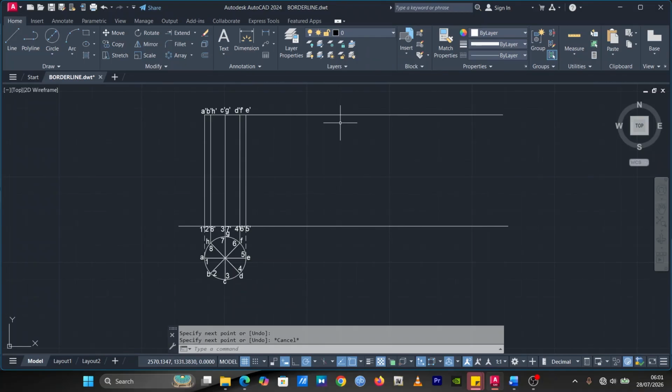So after getting the 79, we know that they are intersecting 8 times. So we are going to divide your 79 by 8. And if you divide your 79 by 8, you are going to get 9.8. That 9.8 is what you are going to use to section this side to be able to draw your base.